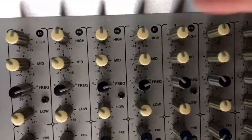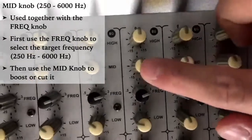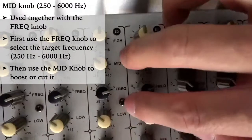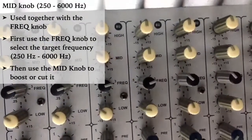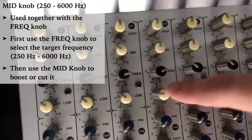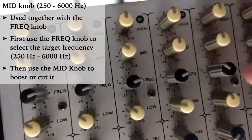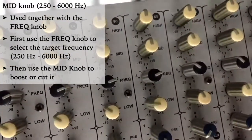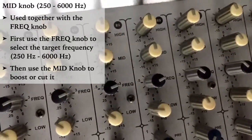My voice. Now you go down to the second one, which is the mid, okay? The mid function goes together with the third knob. This one is a frequency, okay? The mid function allows you to choose the frequency range that you want to boost or cut. It allows you to control anything from 0.25 to 6. 0.25 means 250 Hertz. 6 means 6000 Hertz. So you can individually select that part of the frequency that you want to control.